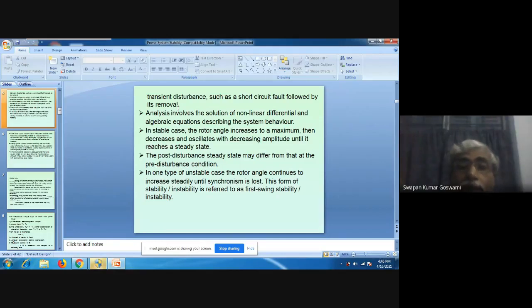Now, sometimes when a short circuit occurs, there are circuit breakers and relays, that is, protective systems installed in the power system, to identify the fault. This protective system will identify that there was abnormal current flowing, because if a short circuit occurs, current will rise abruptly. Why will it rise abruptly? Because the voltage was the normal voltage and is becoming zero, this voltage is dropping in the fault impedance. So a large current is flowing.